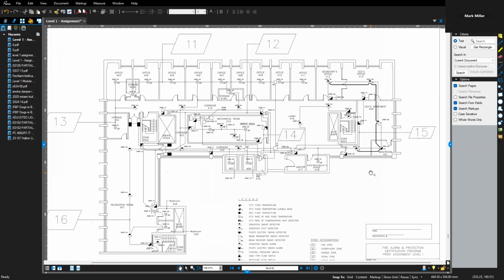But because it's a sounder base, it's also going to be sending the signal back to the main fire alarm control panel and setting off the entire building. So the CEO will know that the alarm is coming from inside his apartment, not just somewhere else in the building. Where it is doing dual duty, being a smoke alarm and a smoke detector at the same time. So that is what we have there.